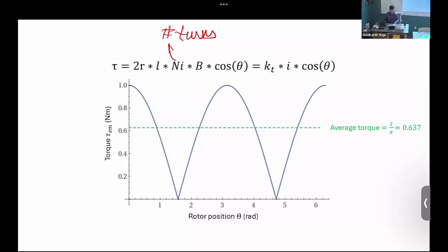A lot of harmonics, right? You can resolve it into a DC component, and then you can resolve it into an AC component. The problem with those AC components is they are not going to provide a continuous torque. We just saw what happens with an AC component. It makes the motor operate like a pendulum, right? So it's going to create oscillations on the rotor structure when you have AC components. So we don't want to have this much oscillation in our torque, right?